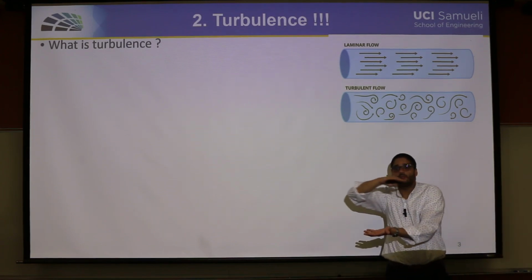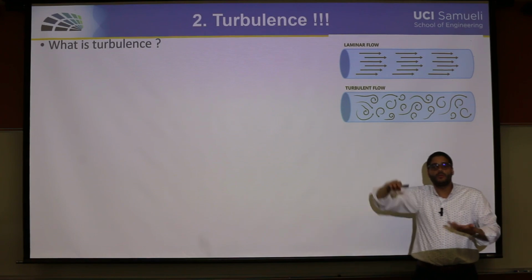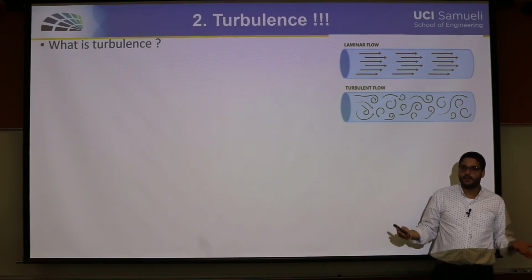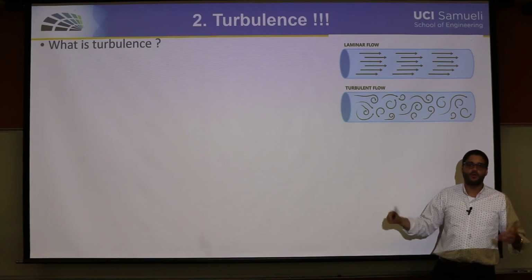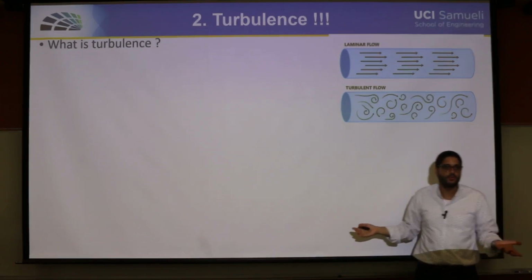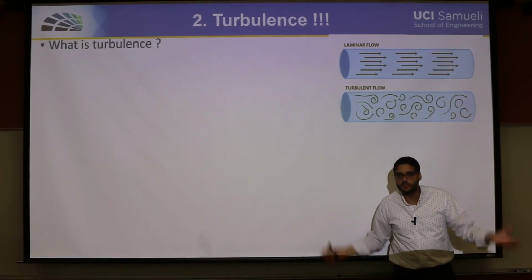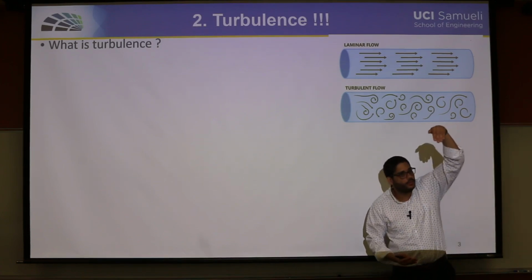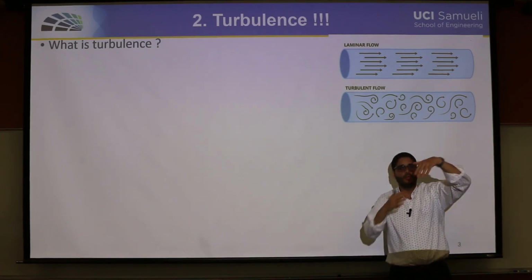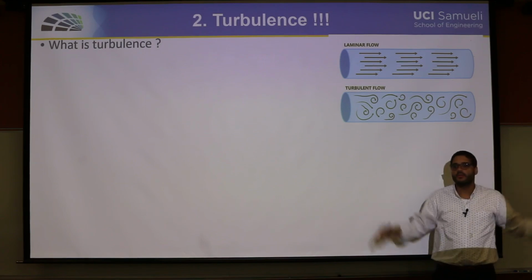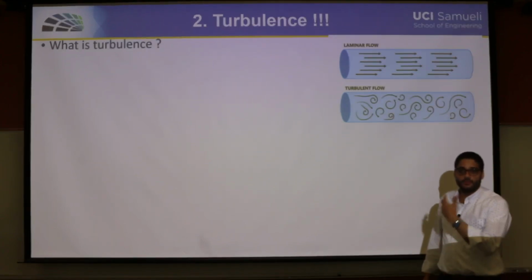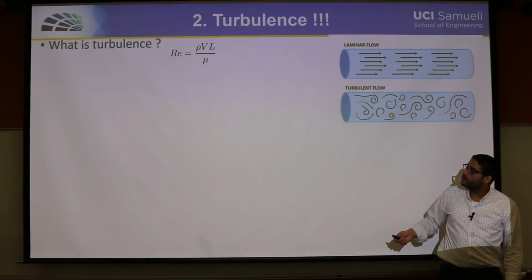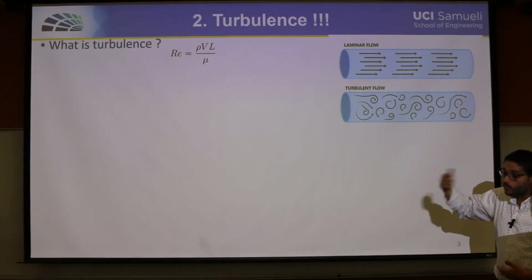that nice quiet flow that we know is no longer governed by the simple diffusive term in the Navier-Stokes equation, because you have momentum transport, you have a velocity field coming normal to the mean stream, and everything is changing. And this mainly relies on the Reynolds number: when the Reynolds number increases, the turbulence becomes more and more.